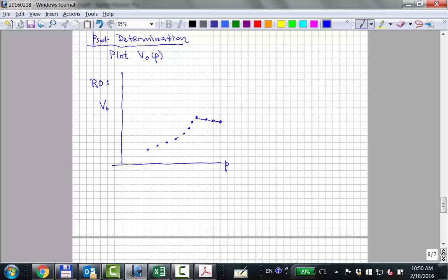So you do kind of a trend analysis, and where these intersect is what you're going to call the bubble point. They don't look for the first bubble of gas, okay? Their eyes are not that good. So they're basically looking for this discontinuity in oil volume versus pressure.